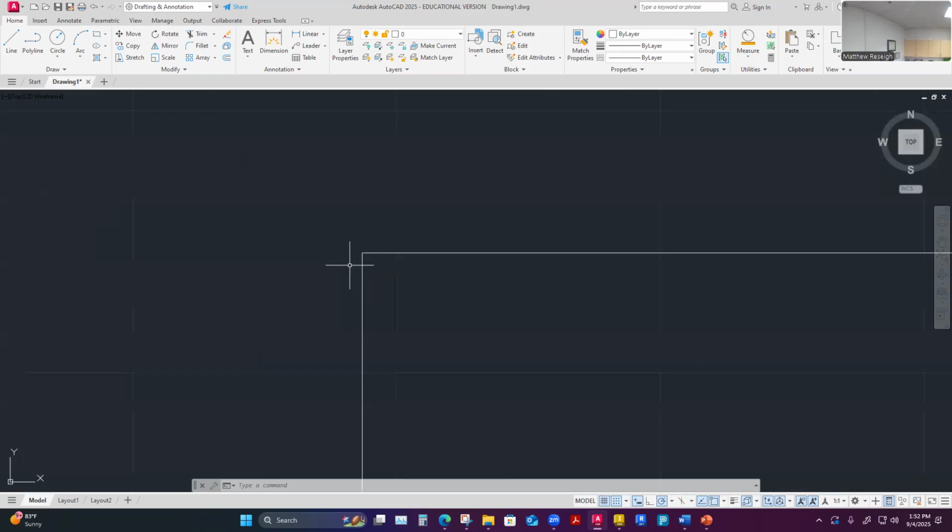That's kind of frustrating. What you have to remember is to input, I think at any time in the command sequence, what the radius is. My go-to, if I'm looking at my command line, is to specify a radius. Generally, fillets are done by radius and not by diameter. So I'm going to pick R for radius. I hit R, enter. And then it says specify the fillet radius.